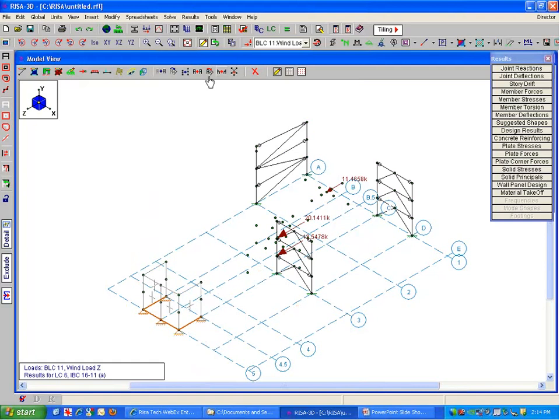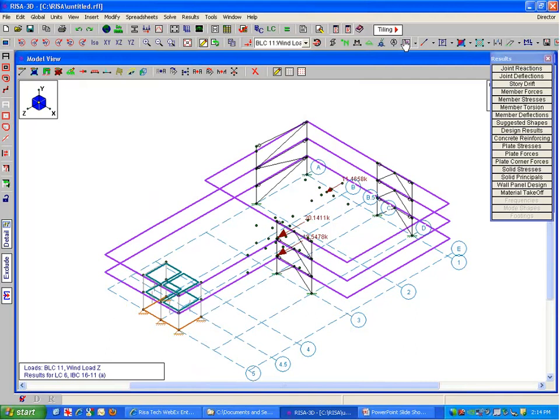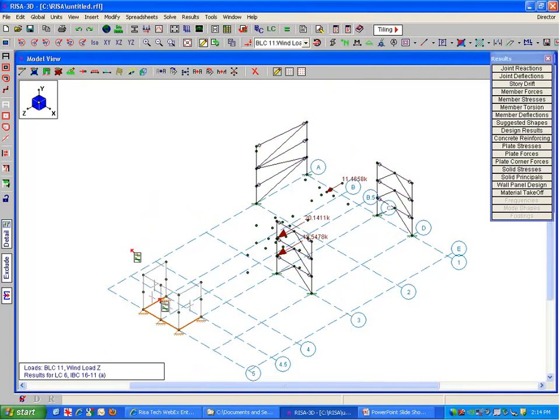So once you're finished with your design in here, you can use the director button. Also, just to make a mention too, if there's any loads above and beyond that you didn't account for, you can come in here and load up that lateral system. You can either load it into the diaphragm, or load it directly into a frame or into a wall and add things like that.